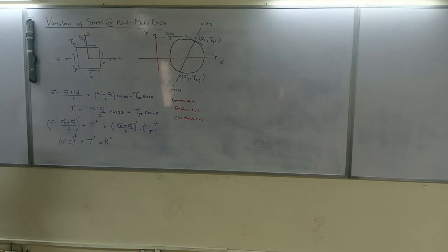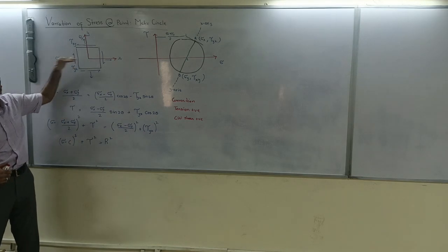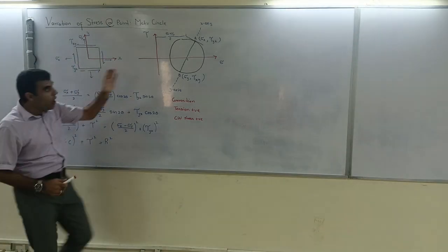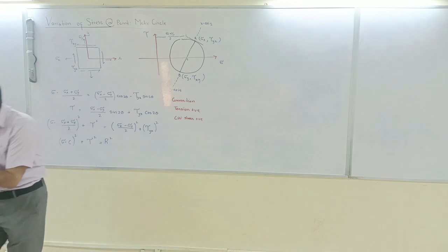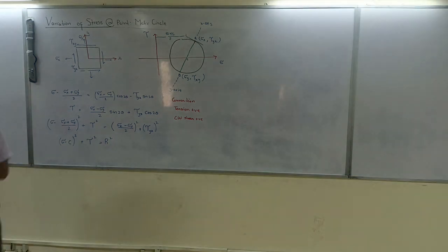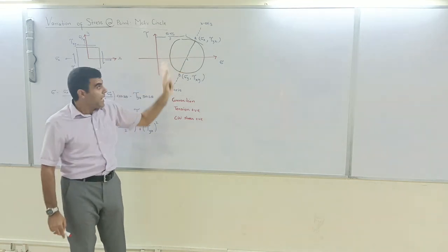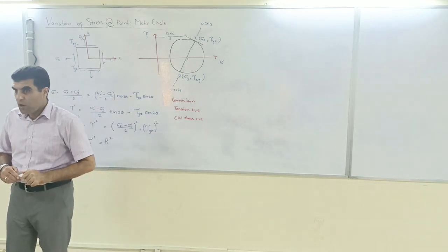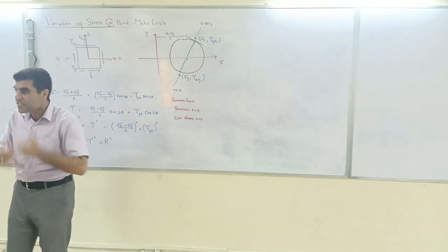I think 4 or 5 times now I have told you that your theta within the element is equal to 2 theta on the plane on the Mohr circle. So the Mohr circle gives us the maximum stresses in the location where the shear stress is 0. This is called principal axis. Why do we call it principal axis? Because this gives you principal stresses, the main axial stresses.